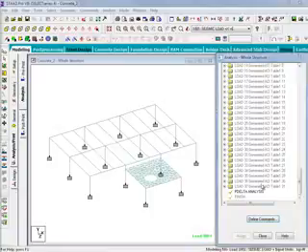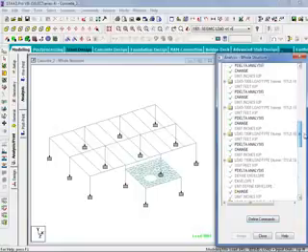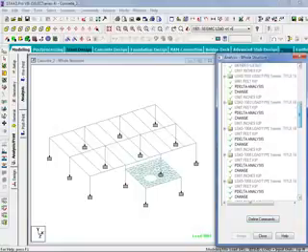Let's also scroll up a little further in our analysis dialog. Here I can see that a p-delta analysis and a change command has been added after each of my IBC seismic load cases. This will instruct STAAD.Pro to analyze each load case individually and then reset the stiffness matrix before analyzing the next load case. And this would be a requirement for defining any IBC seismic loads.